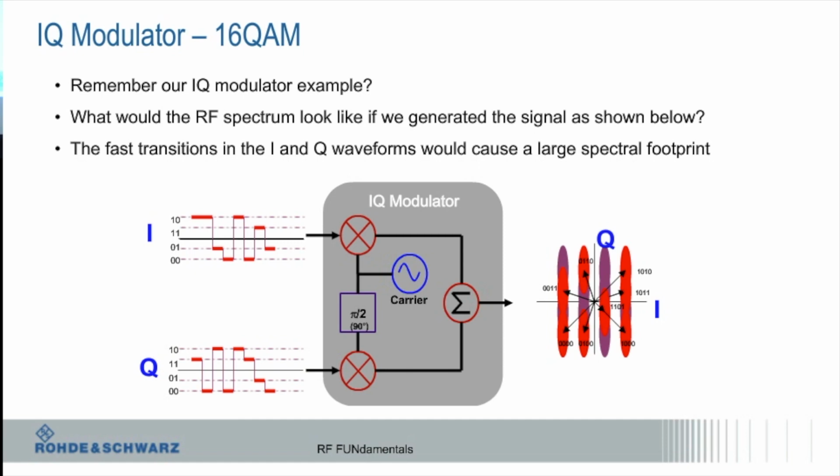And you often find that if you take a transition from the lowest voltage, maybe down here, to the highest voltage, obviously that is going to require the most current, the most potential nonlinearities, and the more settling time. So a lot of these are really designed around trying to minimize that.